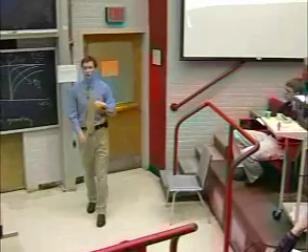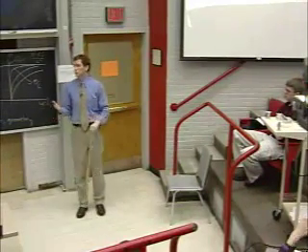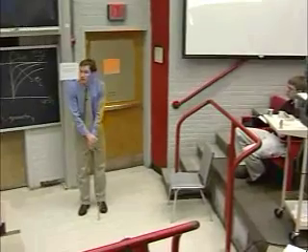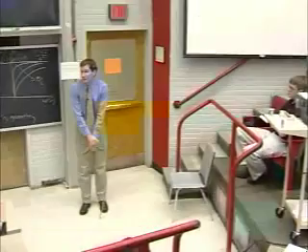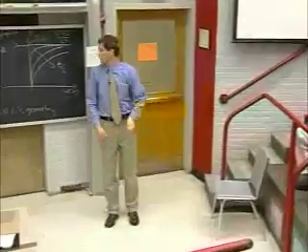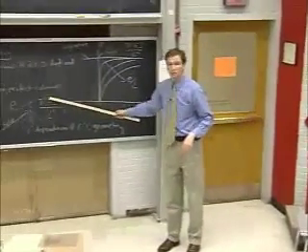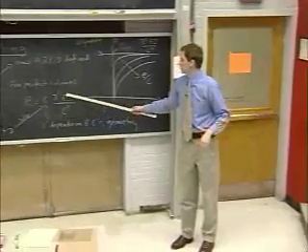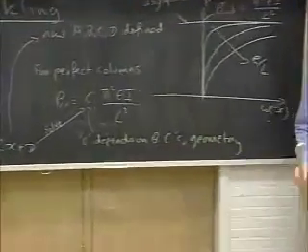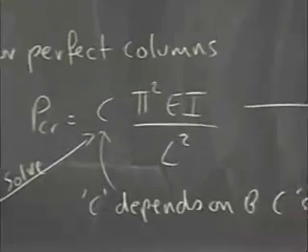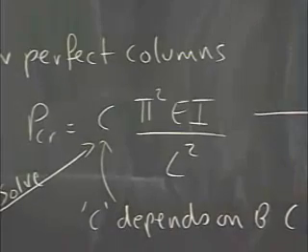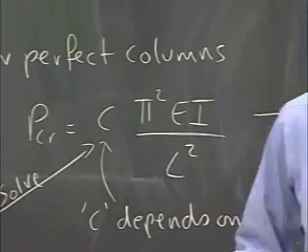Failure of a structure may have nothing to do with the material that it's made of, and a good example of this is buckling, which is a collapse of the structure. It owes something to the stiffness of the material, but a lot more to the geometry, the length, the cross-sectional dimensions of the structure. So when we talk about failure, it's failure to meet a structural design purpose, not necessarily just a material failure, although that's often part of it.